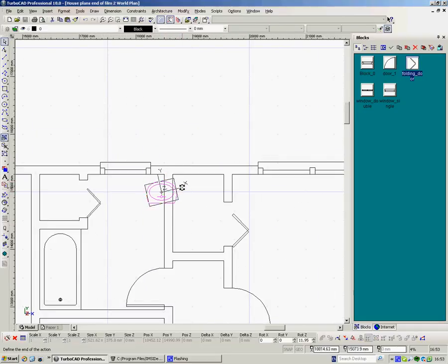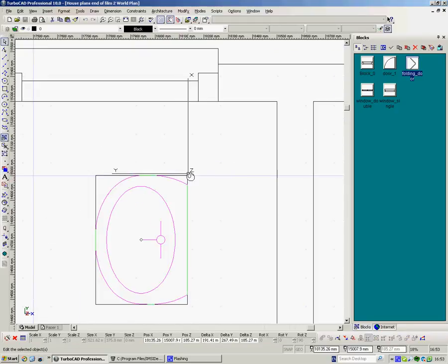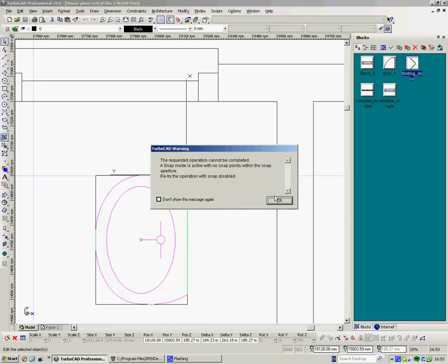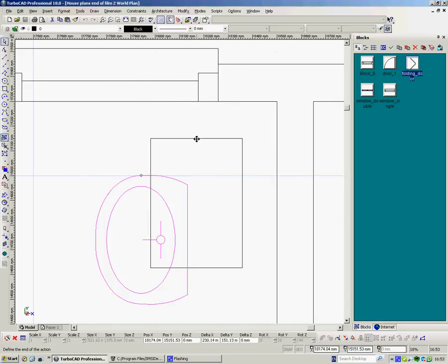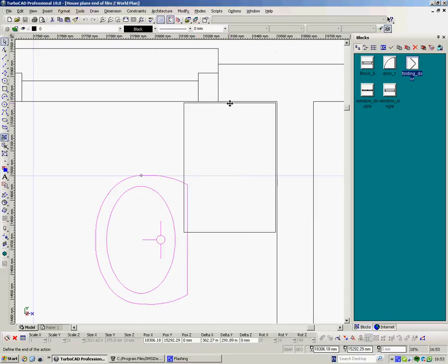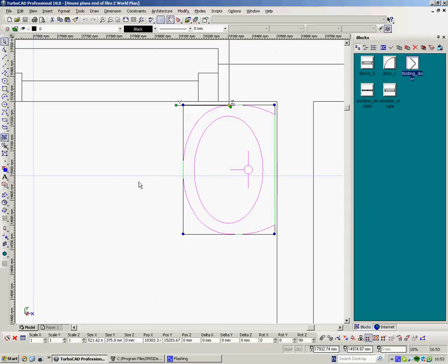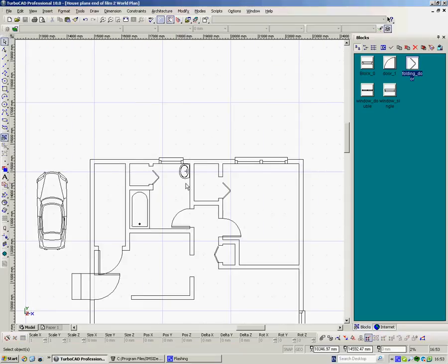I want to rotate it 90 degrees, I should think, so I'm going to go tab, tab, tab, 90 degrees. Hit return. Here we are, there's the wash basin, and obviously I can pick up the origin with the D, snap it to a corner over here with a V. There I got it, let's snap it to that part there with a V. Take that up there, and I can put that there, I can snap to that point or give it a bit of space, whatever I need to do. And there's the wash basin in.